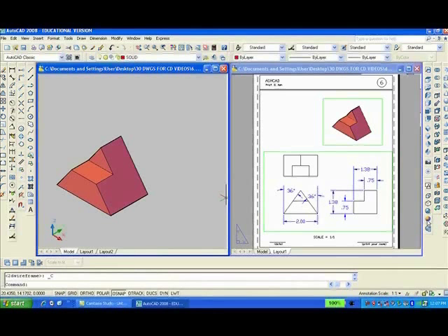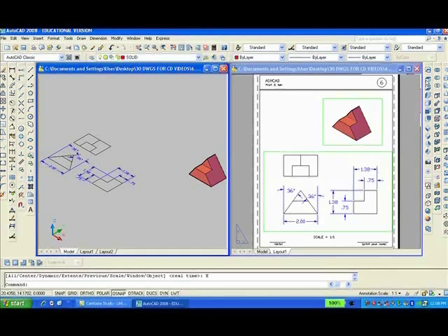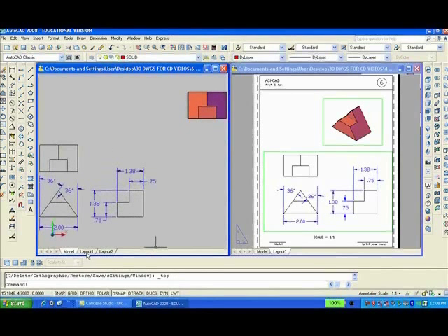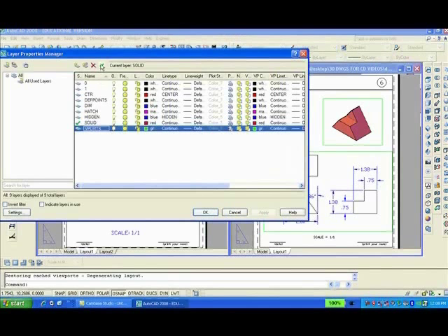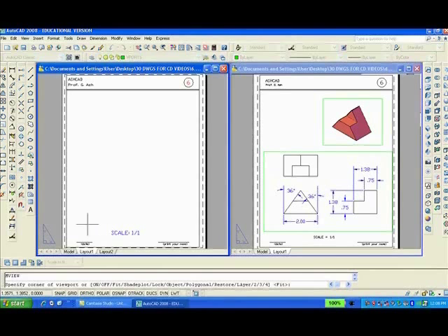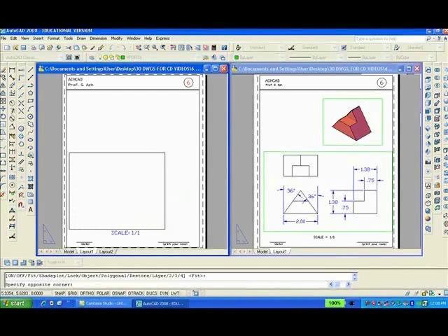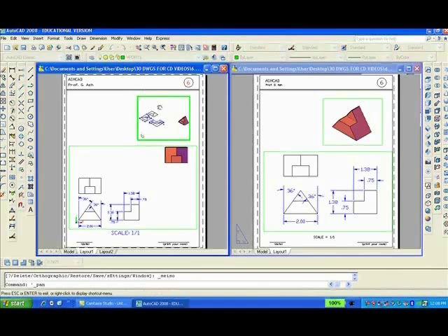It looks okay, so I'll Z, enter, E, enter, move to top view, click on layout button, click on layer button and make layer viewport current, take off snap, type MV, enter, make a large window, enter, make a smaller window, enter, double click inside the small window, go to southeast isometric, pan and zoom, pan,